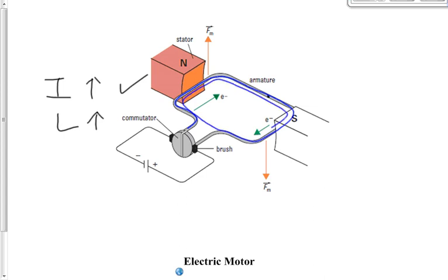You end up having a bunch of loops of wire go around. So now what we've got is 3 times the magnetic force there because we've got 3 times the length. Okay. This doesn't matter, right? This doesn't matter, but we still have 3 times the length of the part that does matter. So length matters, yes.